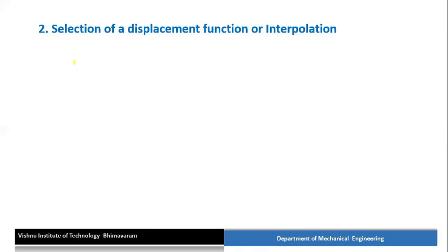So the FEM, this finite element method, is one in which the continuous quantities such as displacement throughout the body are approximated by its discretization. So it is composed of a set of piecewise continuous functions defined within the finite element domain or finite element.